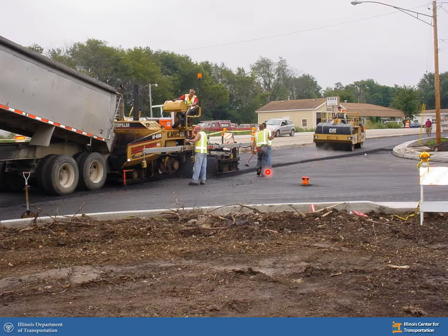But we have challenges in mat thicknesses, especially when you have an intersection and we have crown in the road for drainage. You can see maybe this section of pavement looks quite a bit thinner than this one over here. So we have variation in the mat thickness as we go along. This might be one where if I'm doing a yield check in this area, I might calculate a theoretical before I get out there in the field. This is going to take a little bit of math.